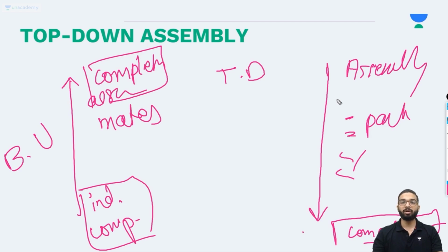We don't always have an assembly ready and we cannot create all the parts in the assembly itself. So while creating assemblies or designs realistically, it is always a hybrid between the bottom-up approach and the top-down approach. Let's say you've created some random assembly over here and then you need to create a new part, a simple part like a pin or something similar. You won't create a new part, model it, save it, and then bring it into the assembly. You can simply create it there itself, and then place it wherever you want, or rather create it at the place you want.